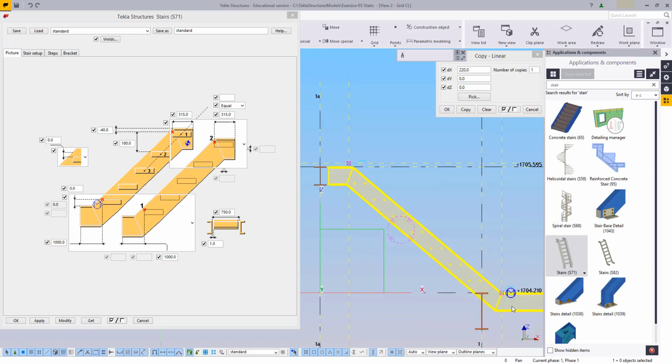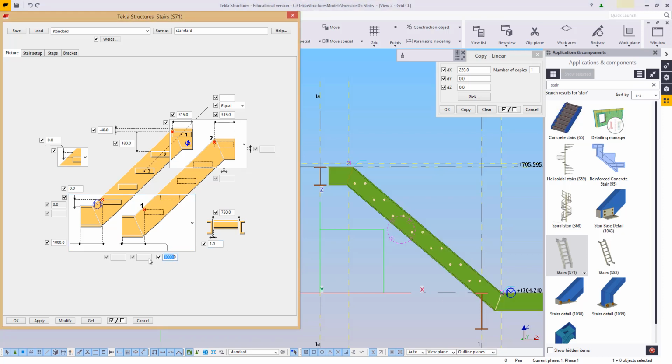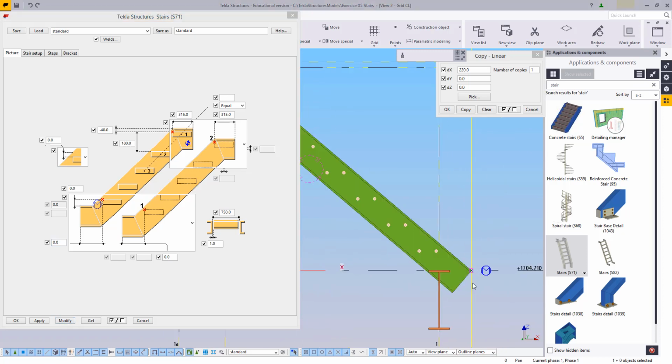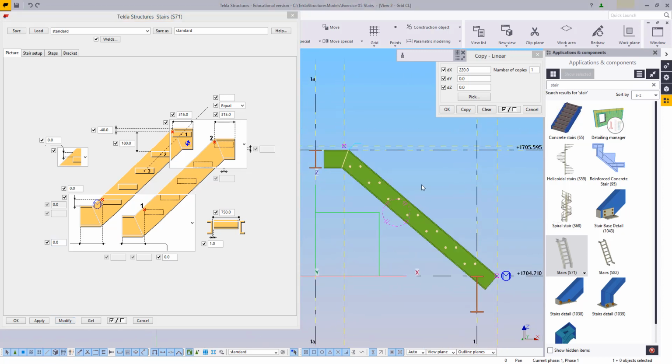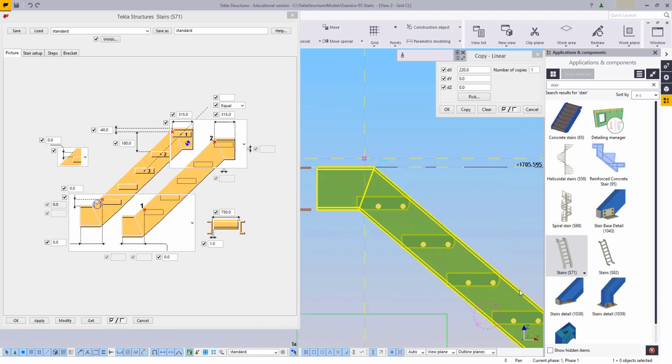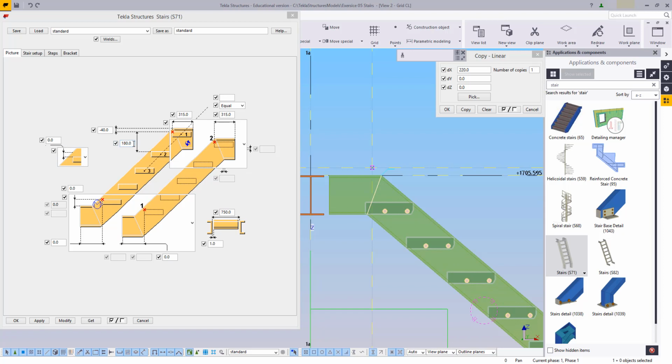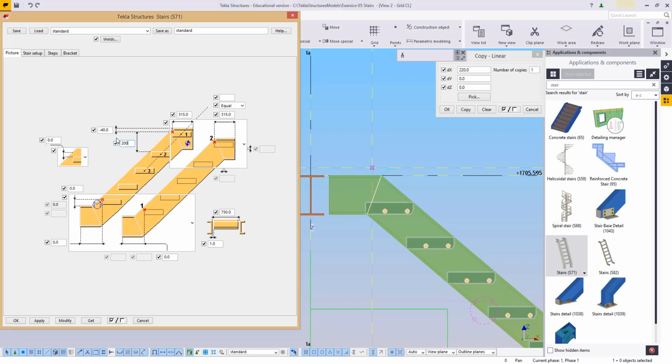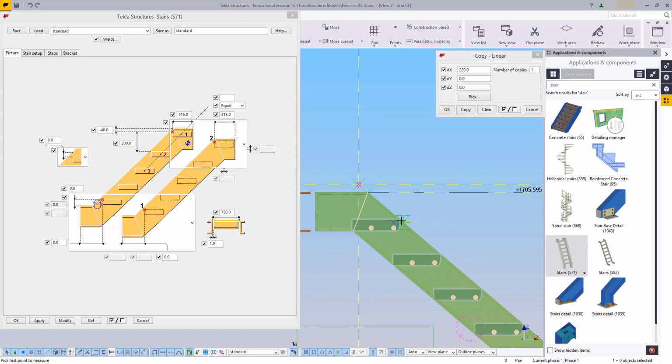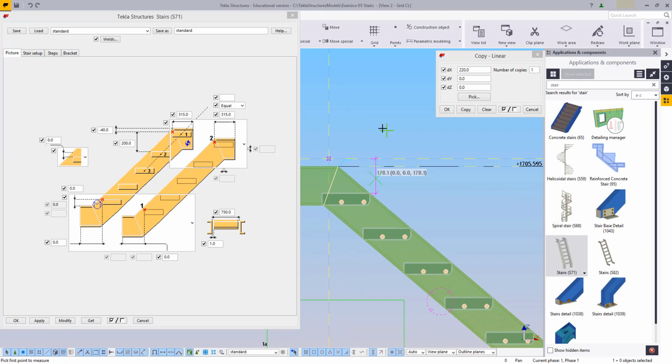Now, as for the bottom, we don't really require it to stick out any, so we're going to make that 0. Next, I'm going to use Shift 2 to get a nice see-through picture, and I'm going to change my distance between stairs to 200. Modify that. Then I'm going to quickly take a measurement just to make sure that it is 200, which it isn't.